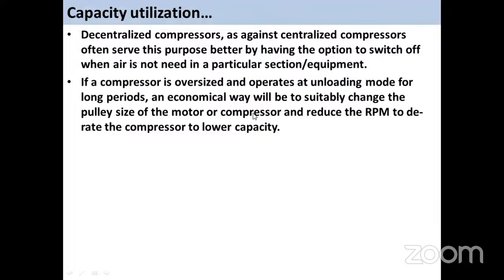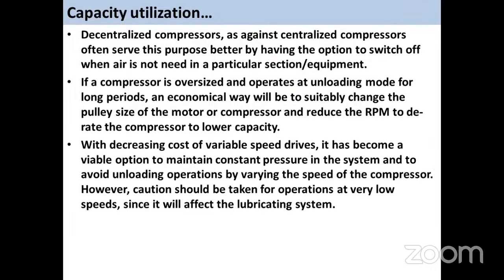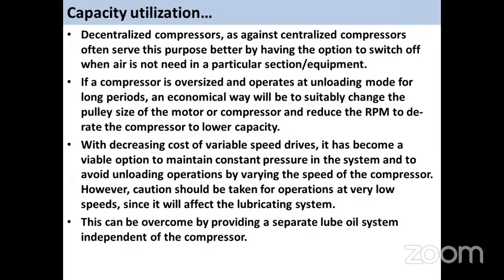Pulley size: if the pulley size is reduced, the speed of the compressor will get reduced. With decreasing cost of variable drives, we can use variable speed drives also. Since it will affect the lubricating system, this can be overcome by providing a separate lube oil system independent of the compressor.